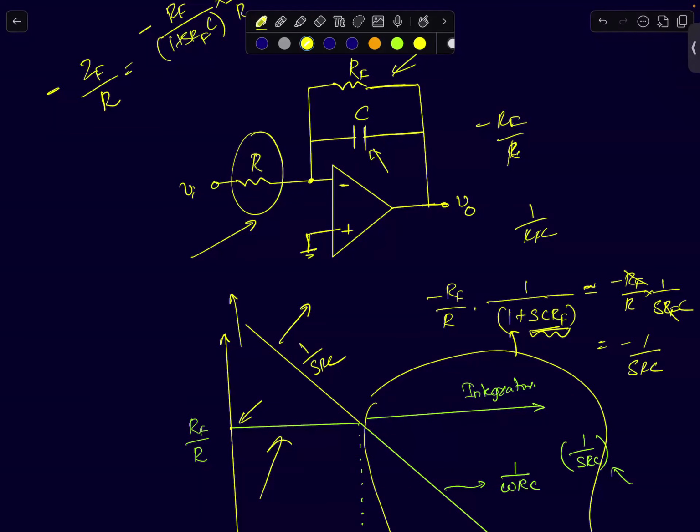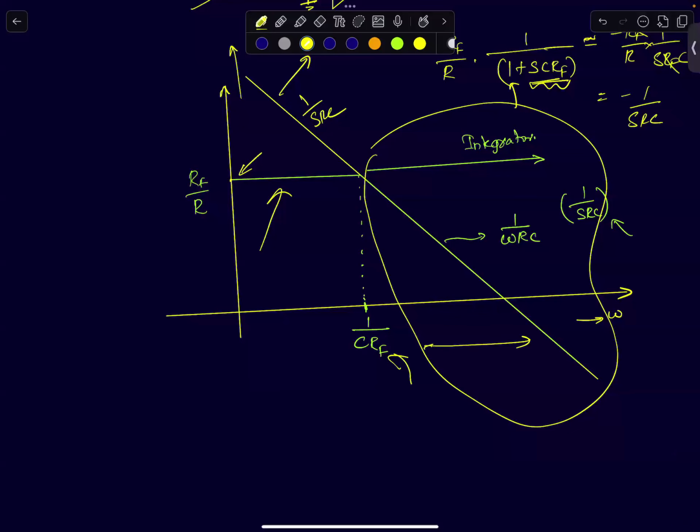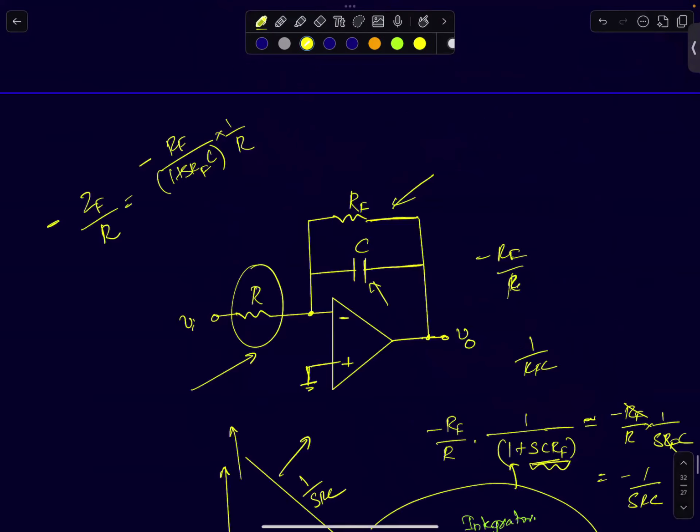Generally, integrators are not used in open loop as they are. We will take some examples later and see where integrators are used. They are often placed inside bigger global negative feedback loops, which ensure that the outputs don't blow up. But if you are going to use it in open loop, you will usually need this integrator to act like an integrator for a range of frequencies. You can choose your value of RF to ensure that the integration behavior is guaranteed in the range of frequencies you want. So practical integrators will often have a resistor in the feedback path.